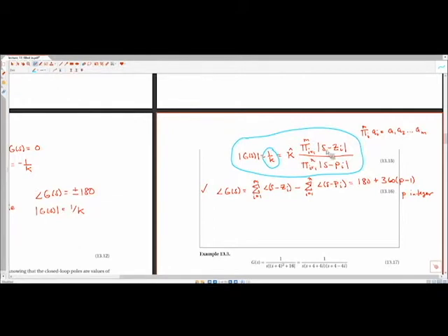If we have some value of S that's along the root locus, we can write this expression composed of all the magnitudes of vectors running from the zeros to that value S, all multiplied together, over the magnitudes of vectors running from all the poles to that value of S, also multiplied by the inherent gain of the system, and that's going to equal 1 over k, which is the variable we're varying from 0 to infinity when we plot the root locus.